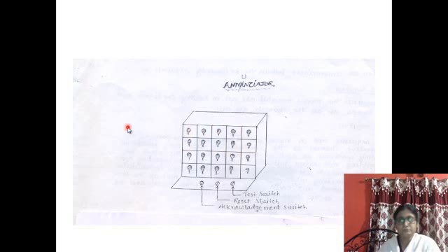To produce the visual signal, whenever any failure occurs in a particular channel, the corresponding channel signal lamp will glow. And for all the channels there is a common hooter to produce a loud sound to draw the attention of plant personnel.